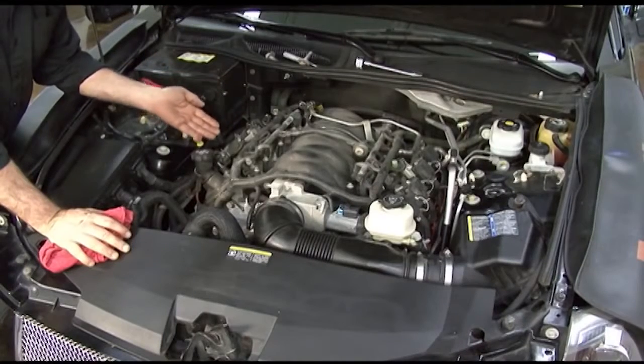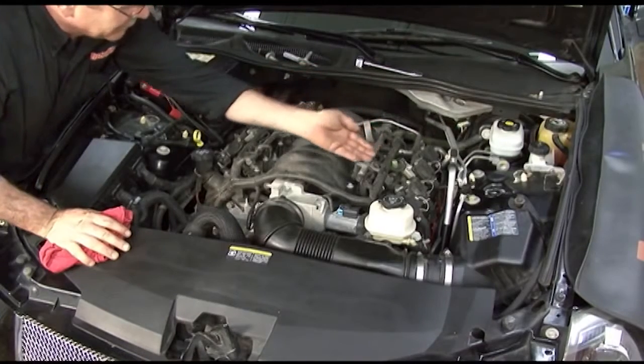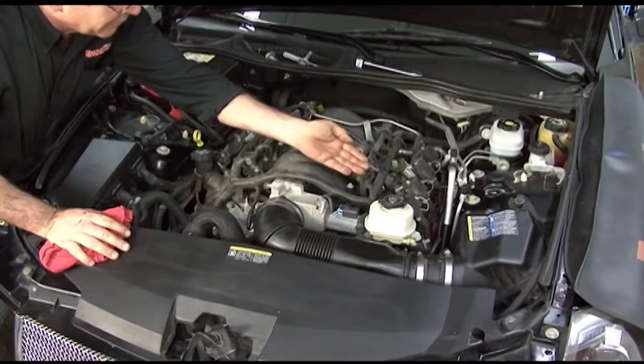With experience, you should be able to feel the difference between a misfire that's related to only one or two cylinders as compared to one that's occurring in most, if not all, the cylinders. Sometimes the cylinders that are misfiring can all be on the same bank on a V engine. You need to recognize when this is occurring, determine what the likely causes are, and consider how this type of misfire will impact your diagnostic routine.